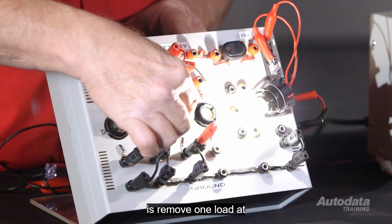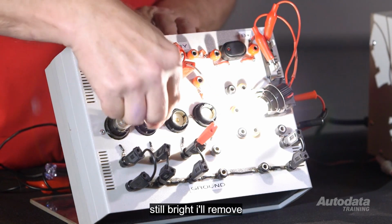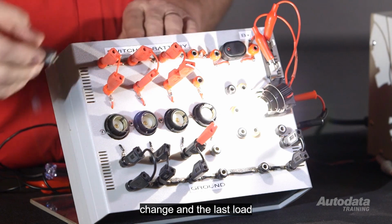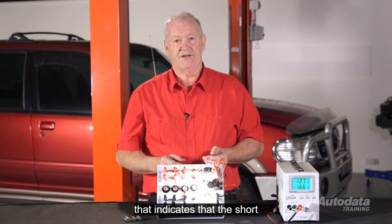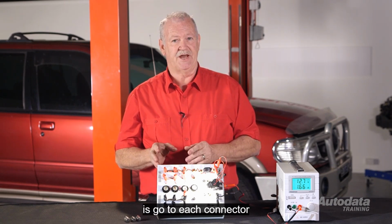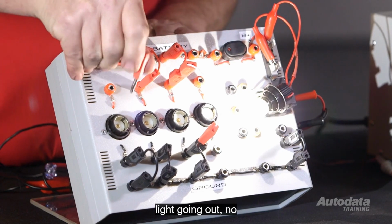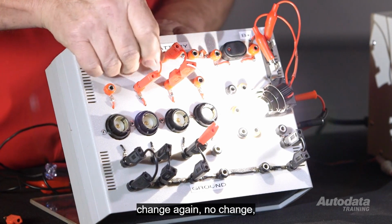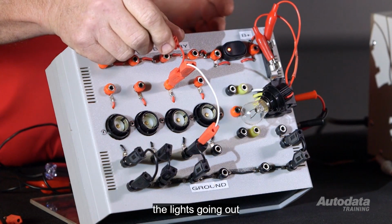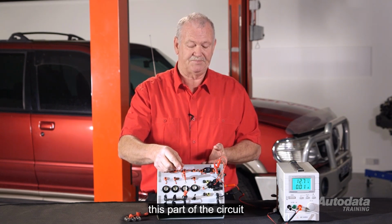Next thing I do is remove one load at a time. The light's still bright. I'll remove the next load, no change, and the last load, still no change. That indicates that the short is in the wiring. So now what I need to do is go to each connector and disconnect, looking for the light going out. No change. Again, no change. The light's gone out. So obviously, the fault now has to be in this part of the circuit.